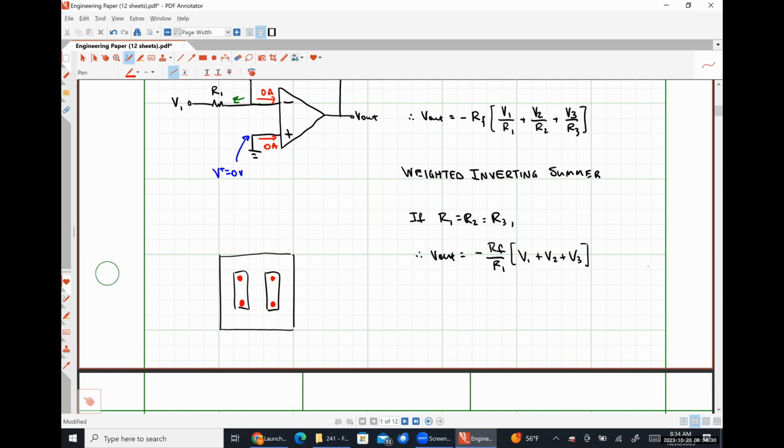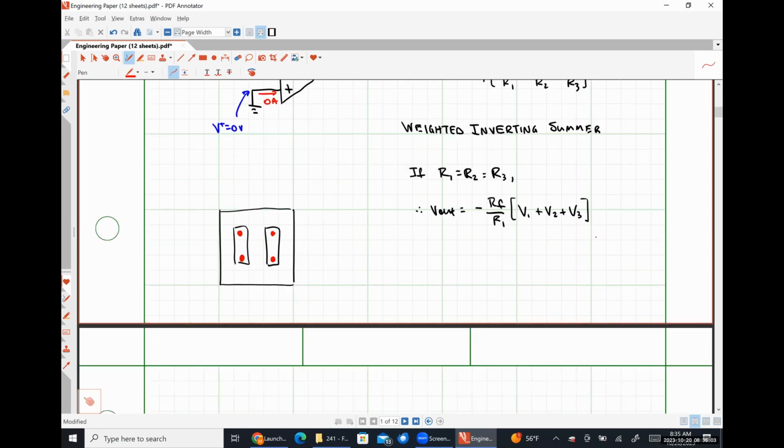All right, so to this point, let's review what we've talked about. We've talked about how to make signals larger and smaller if we're okay with having an inverted signal. We've talked about how to boost signal power effectively with a unity gain buffer, or just make the voltage larger with a non-inverting amplifier. Now we have seen how the mathematical operation of addition is carried out using op amps. So let's now talk about subtraction.